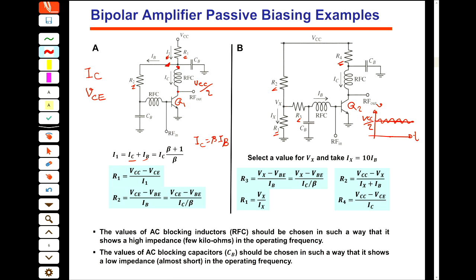So you have a biasing point, and we say that this is the DC VCE. And then your RF signal is going to come on top of this. So the RF signal is AC. And when it reaches the ground or reaches the VCC, it gets clipped. So to have a maximum output, and this is actually the P1 dB, before reaching that point where it gets clipped, it's better to bias your transistor in the middle.